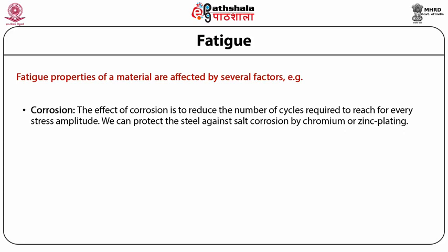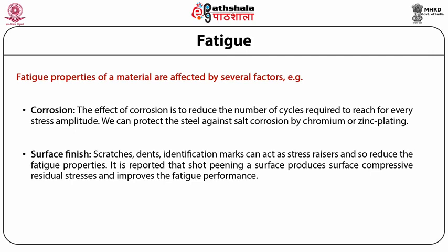The second factor which affects the fatigue properties is surface finish. Scratches, dents and identification marks can act as stress raisers and so reduce the fatigue properties. It is reported that shot peening a surface produces surface compressive residual stresses and improves the fatigue performance.